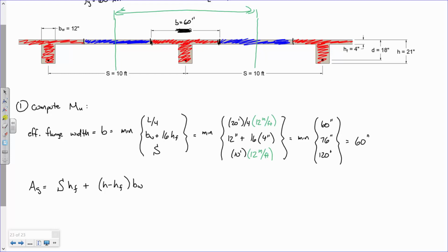But remember, that's already converted as a line load. So it's already 1 kip per foot just on the beam. That's a great question, but we don't have to worry about that because it's already on the beam. But in general, if you had a pressure load, it would be pressure load over what? Tributary width? What is the tributary width? It's the beam spacing, right? Does that make sense? Is everybody okay with this? These are good questions. Everybody good? All right.